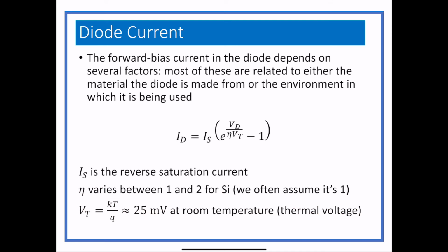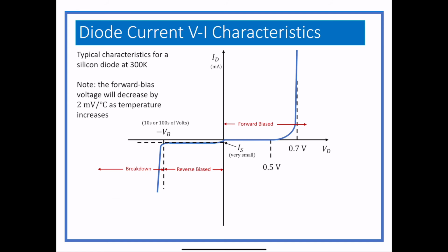Yeah, that is the voltage across the diode. So that is basically what relates the current and the voltage. So we can actually plot that, and when we do, this is a highly idealized plot, you'll see that there really isn't any current flowing through the diode in the forward bias direction until you reach this kind of 0.5 or so volts, and then it overcomes it really fast.